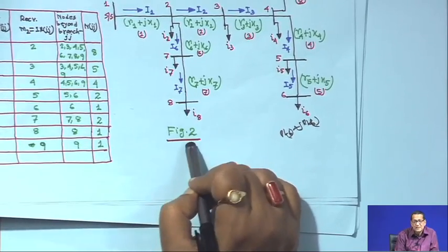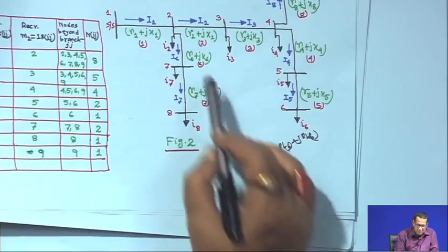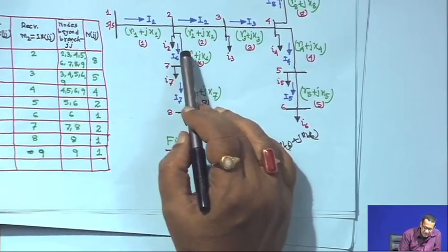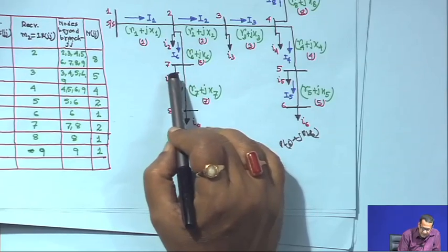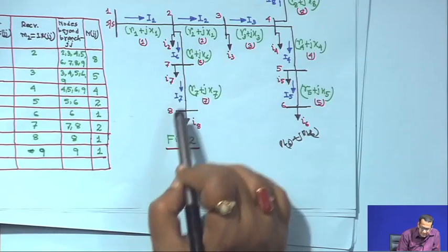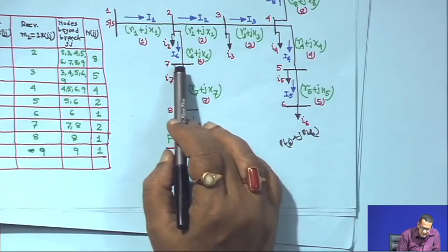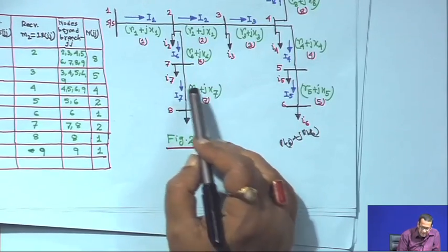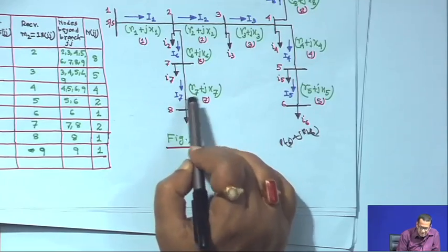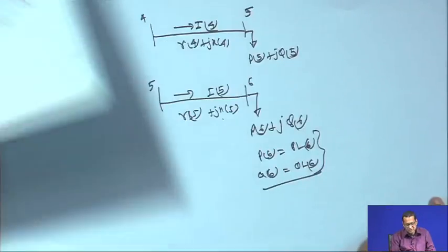Right, because there are no other branches. So, no question of losses; this is only for the last node. But in all other cases, if you take the electrical equivalent of branch 2 to 7, then P7 will be PL7 plus PL8 plus the real power loss of branch 7. Similarly, the total load fed through Q7 will be QL7 plus QL8 plus the reactive loss of branch 7, right. So, this way you have to find out the total load fed through each node.